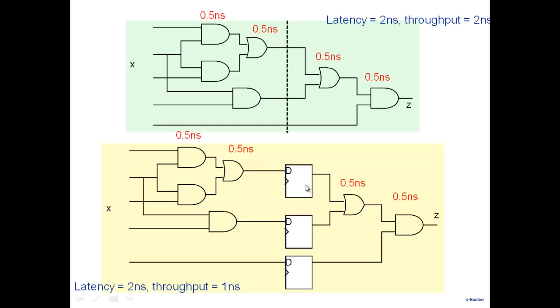Well, no. So this is the point. Here, let's say in this example, the flip-flop delay also you have to take into account, right? Flip-flop delay is not 0. So after a while, if you break it further, then you're not getting so much improvement. The flip-flop delay comes into the picture here. Instead of placing it after 1 nanosecond, what will happen if you place it after 0? Oh, you're saying the same flip-flop, yes. If I place it here.